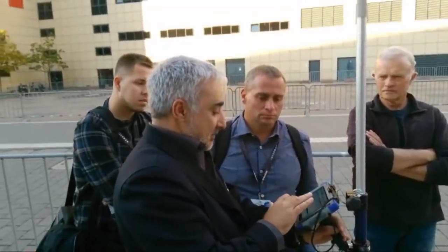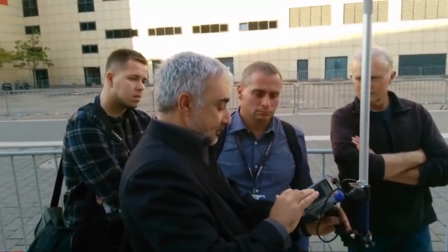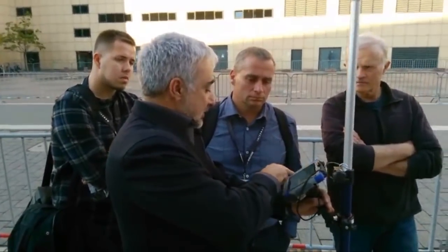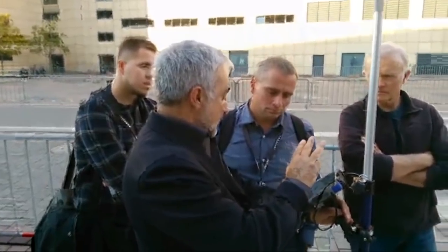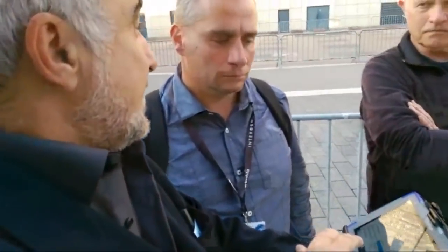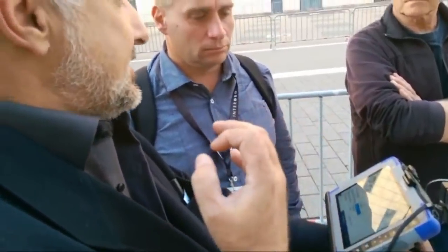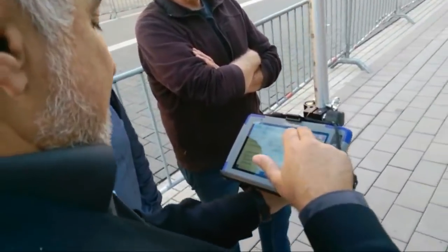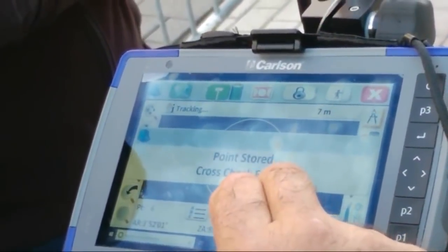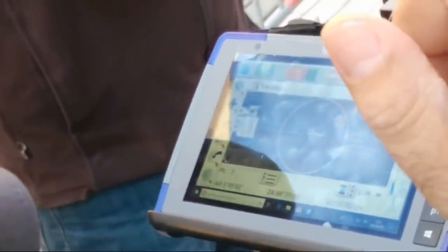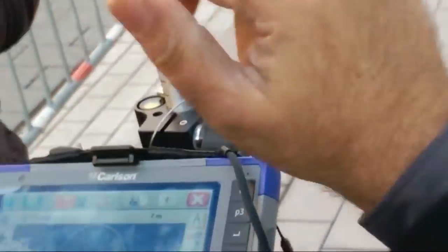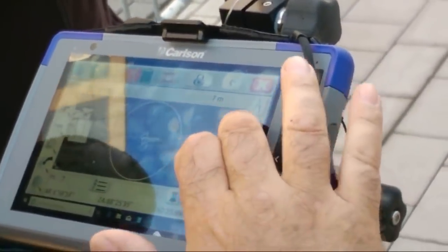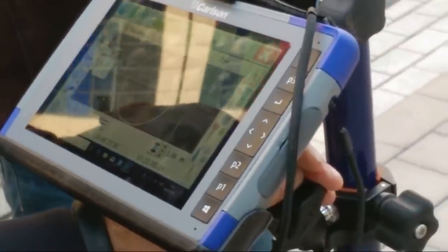So for that, we did something which is hybrid settings. You have the cross check mode, 3 different modes. Automatic requires sighting. So you always know the cross check fails, but it doesn't stop. It tells you. I haven't tested the silent mode in some time. So if I store points now, Cross-check failed, you see, but I can continue. You know something is going wrong, but I can continue measuring. You don't want to stop and say yes.